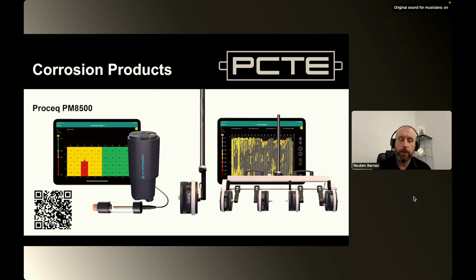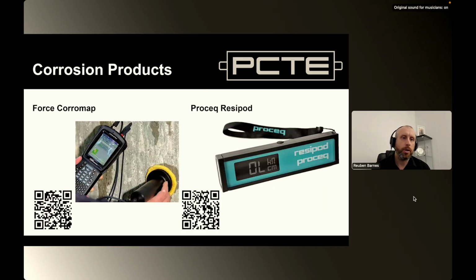There are also some configurations where we can put the reference electrode into a wheel and then into a four wheel, and that assists with data collection. We're also going to talk about the Force Corromap. That's a corrosion rate meter, and it also does half cell potentials. And then we'll also talk about the ResiPod, which is a resistivity meter. These are the main tools that we would generally use when we're looking at corrosion, on top of potentially crack measuring and cover meters and things like that.